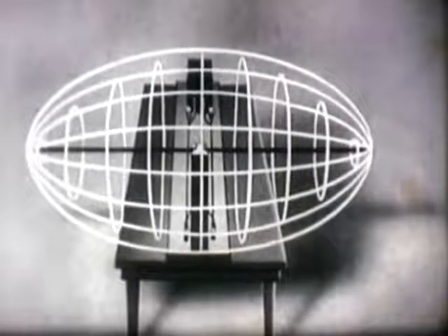Let's examine the kind of radio waves it sends out. The vertical rings represent the magnetic lines. The horizontal rings, the electrostatic lines. Let's say these lines form a single wave, and we'll stick with this wavefront as it is radiated into space. Upon leaving the antenna, the pattern enlarges. It stretches, yet the magnetic and voltage lines retain a fixed relation to each other and to the Earth.